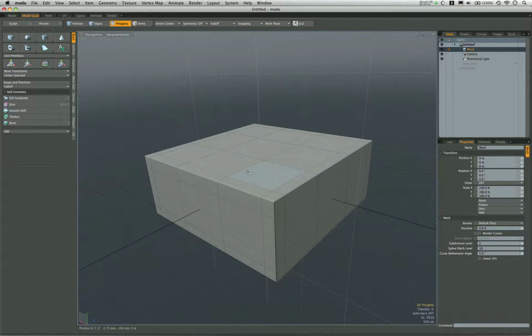And that will help a lot because often we're going to be wanting to decrease the subdivision level on these in order to get a lighter render. And remember, subdivision surfaces are often going to be rendered with adaptive subdivision, so the closer you get, the more polygons are there. And so it's not really going to matter too much how many polygons are in the base here.